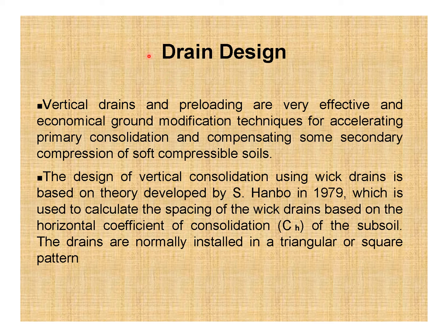Okay, drain design. Vertical drains and preloading are very effective and economical ground modification techniques for accelerating primary consolidation and compensating some secondary compression of soft compressible soils. The design of vertical consolidation using wick drains is based on theory developed by S. Hansbo in 1979, which is used to calculate the spacing of the wick drains based on the horizontal coefficient of consolidation C sub h of the subsoil. The drains are normally installed in a triangular or square pattern.